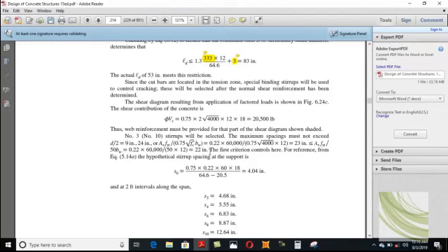These 4 or 5 criteria are used for shear design, and from them we will determine the spacing of stirrups. So you see that this is a design spacing criteria that gives you 4.04 inches, because 20 is the shear capacity and 64 is the maximum shear.